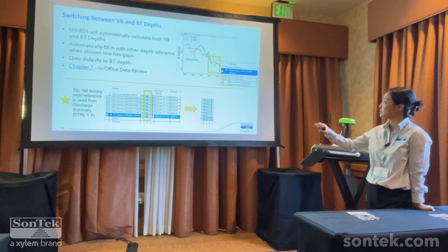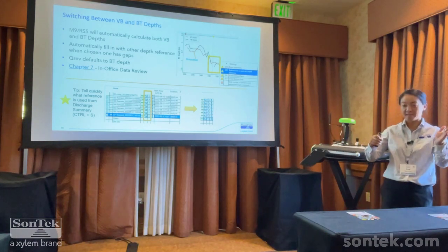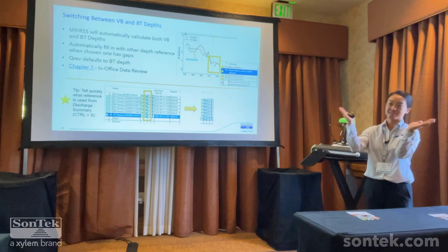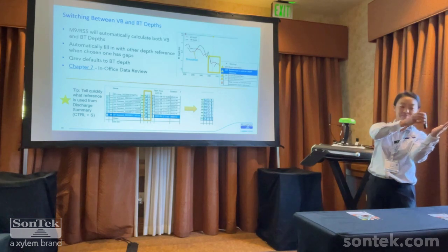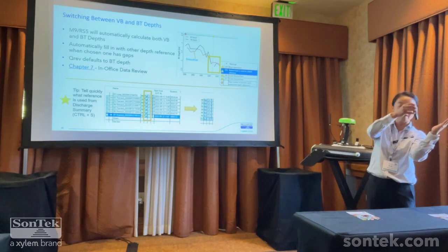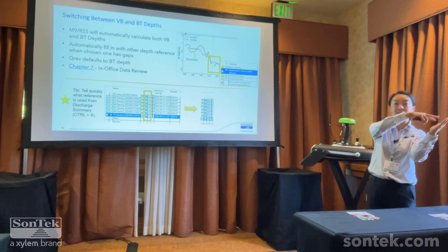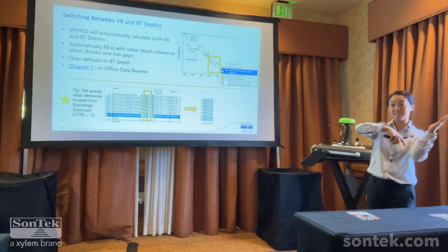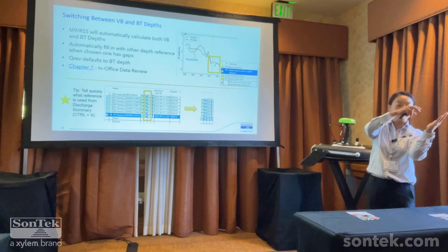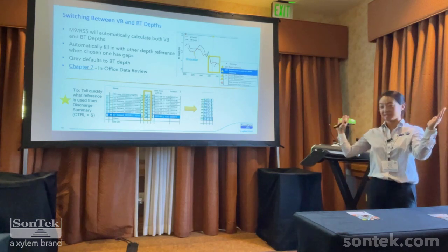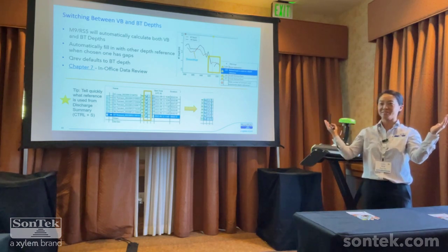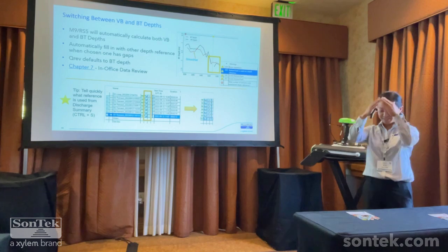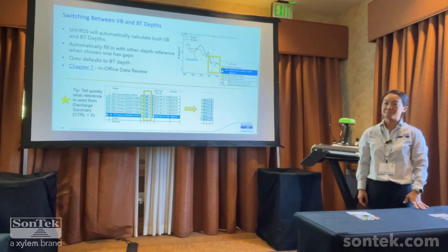at an edge like this, for example. But what ends up happening is that if you have a slope, usually sites are more like this and not perfectly vertical. So if you have a slope and you're looking at the vertical beam, it's going to map out the slope for you. But if you're looking at the bottom track depths, you're getting an average, and so you're getting lower numbers here and then deeper numbers here. And as you move along, that slope is going to be slightly different, but it's also going to be different on the other side as well compared to the vertical beam. And so actually the areas even out, if that makes sense. Yeah, you kind of have to see the whole picture. Sure. Yeah.